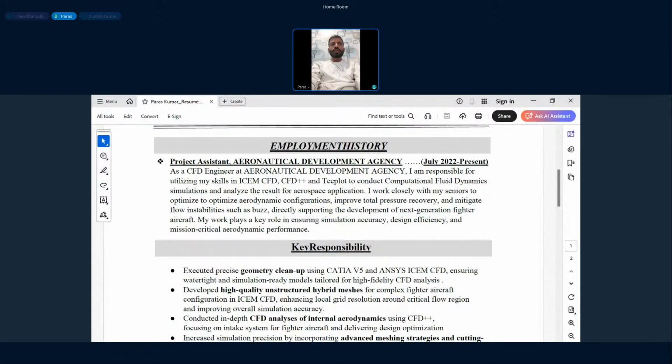Sir, the advantage is that it will help with torsion and the bending moment on the wing. When moment comes, the wing will fluctuate, so the under-wing intake will help reduce this bending moment or fluctuation. That will be very little because the air intake weight is very low, so it will not have much inertia.